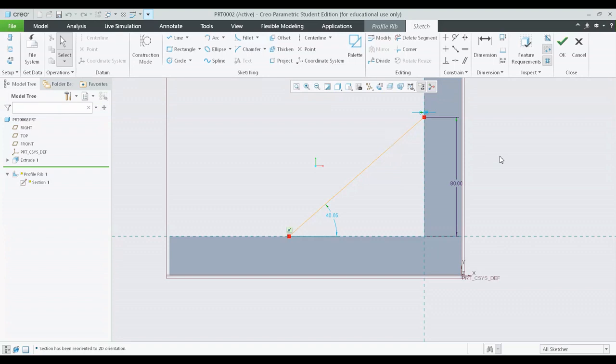Now you can see the difference between general sketching and rib creating. The difference is, for the rib, we do not require a closed sketch, or a closed loop. It can be a single line that connects two edges. So this is a single line which is connecting two edges. I'm getting a symbol over here of a dark shaded point, which indicates that the line is an open end. But still I'm comfortable with this because a profile rib is created in this particular method.